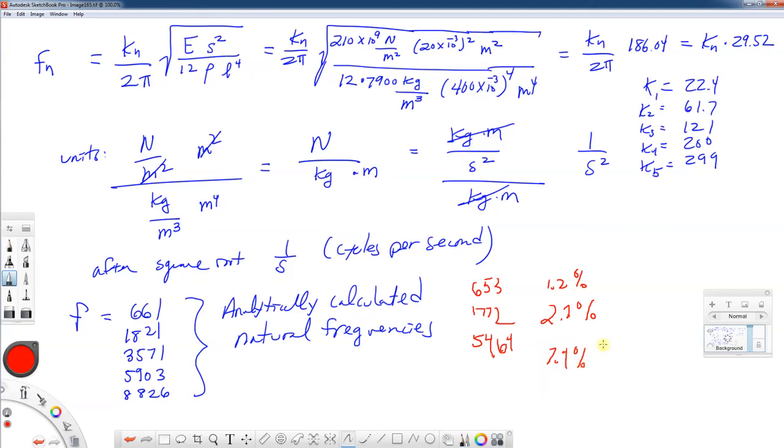So when you do a natural frequency analysis, this is one of the things you have to be a little bit careful about. At high frequencies, your numerical analysis may start to have some more inaccuracies than at low frequencies. For a car or something like that, you may be interested in frequencies that might cause some excitation due to your road travel. So a large structure may have some low natural frequencies that get excited just by running over strips on the road or something like that, and it causes kind of a buzzing sound. So you would want to avoid those kind of frequencies.